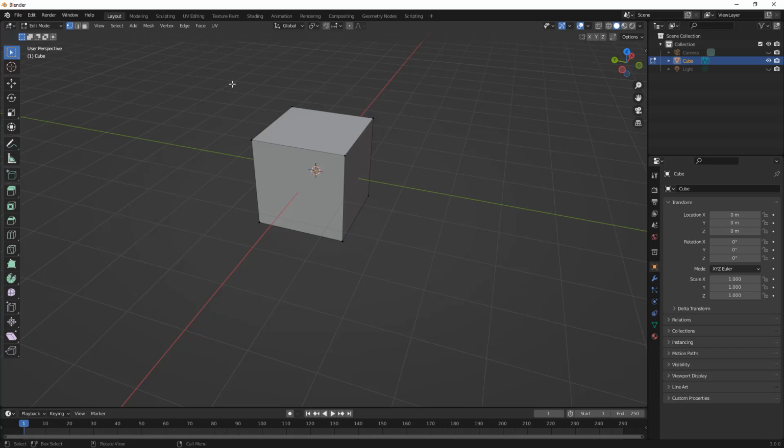If we left click, we can go ahead and deselect everything. Then we can select each of these vertices holding down the Shift key, and as soon as we select all four, that top face is fully highlighted. Again, it's important to remember that in Fusion 360 we have the multi option that allows us to create our selection simply based on what we're clicking on.